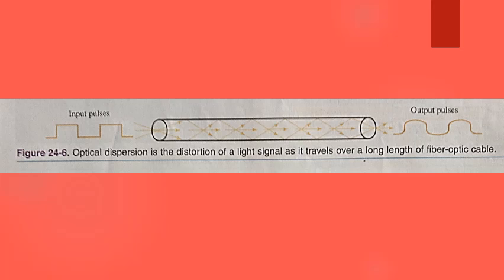A typical pulse is transmitted into one end of the fiber optic cable. Due to the reflection of the light along the core of the cable, the light pulses arrive at the cable termination at different times. This factor causes the original square wave to be distorted in shape. It appears flattened and elongated. A receiver equipped with digital gates can quickly reshape the signal back to the square shape again. However, the process of regenerating an original amplitude or frequency audio or video signal is not always so successful.